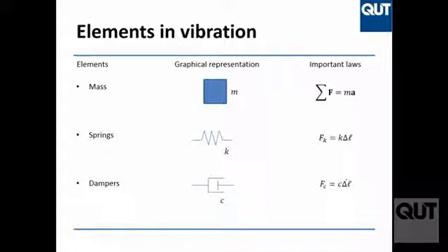It can be a lot of things, but very commonly it's that your front wheels are not perfectly aligned. When they set up your steering, when you change tires and so on, they need to be sure that your front wheels are aligned. If they're not, you get some vibrations on your steering wheel, because your car gets a bit of wobbly motion.